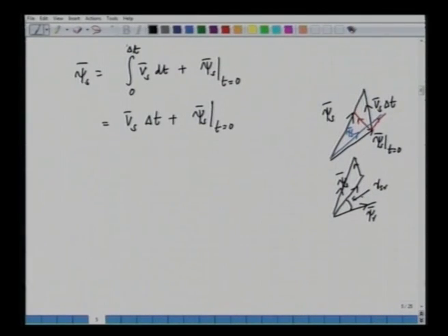If you want to decrease this angle, you can take another situation where the angle is reduced. This is the rotor flux psi R, this is the stator flux psi S, and if you want to reduce this angle gamma SR, instead of moving away, we can move towards the rotor flux vector. This is the resultant of the two, and hence the angle is reduced.